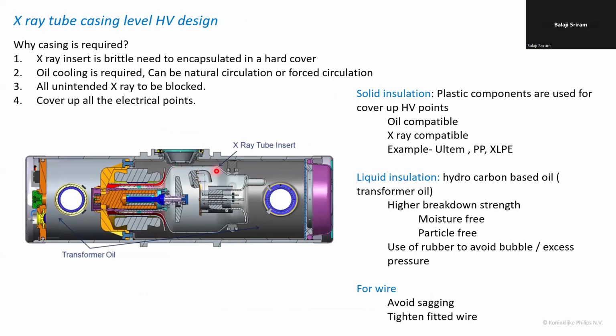One more question: to maintain the surface roughness, do you do corona etching or is there any other process? To maintain the surface roughness, we generally depend on the machining process as much as possible. Then there is baking, taking it to a very high temperature to reduce any gas entrapment, which results in roughness later on. Then we take it to electropolishing to obtain the surface roughness. Okay, thank you.